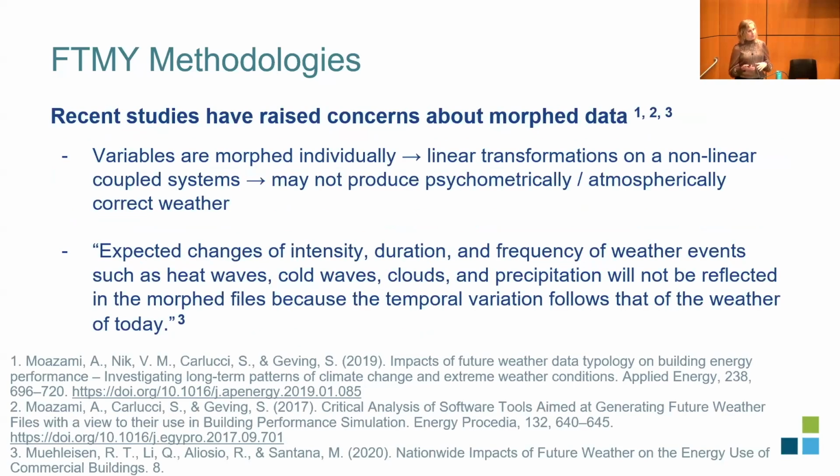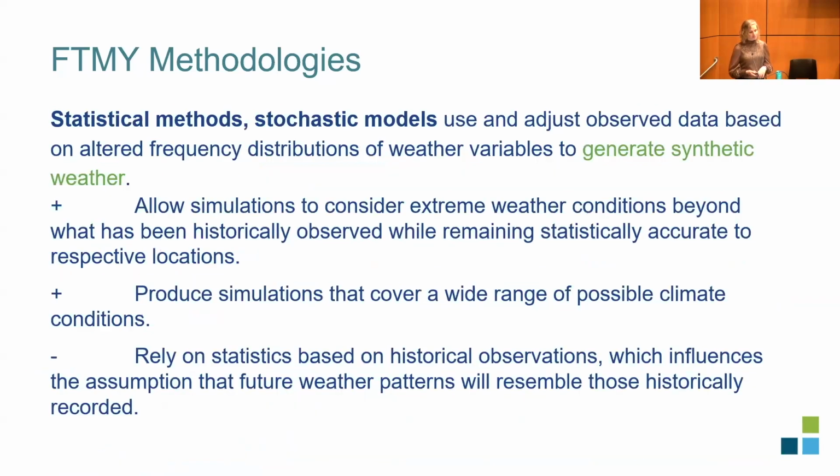The crux of the concern is that you're applying linear transformations to a very nonlinear coupled system, and you're going to end up with a situation that's not psychrometrically accurate. Said in a different way, you get weird combinations of temperature and humidity, which can really affect your building design. Also, if you're just doing these simple stretching and shifting, you're not going to see those changes in intensity, duration, and frequency that I talked about earlier.